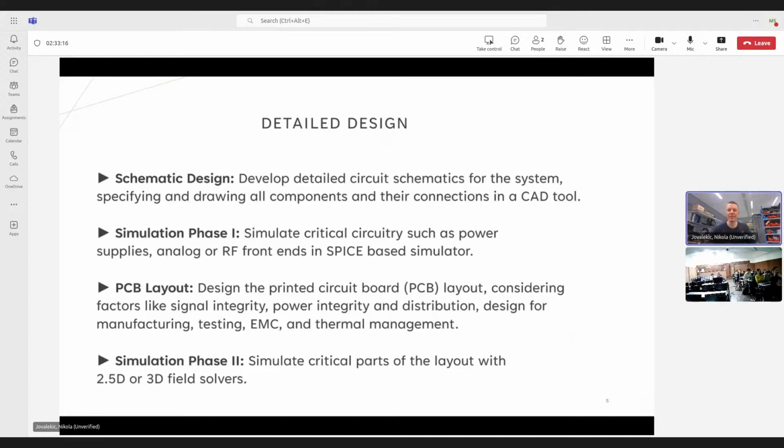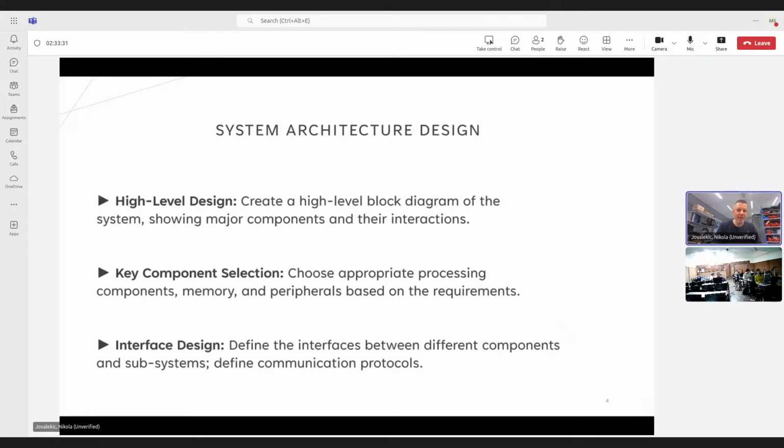Very, very good question. So I will tell you how it works in practice, at least in some of the previous companies I worked for. For example, you do key component selection. The layout team already starts to design libraries with these components, and they already start to do initial positioning of the key components. You didn't even make a full schematic, and they already started.